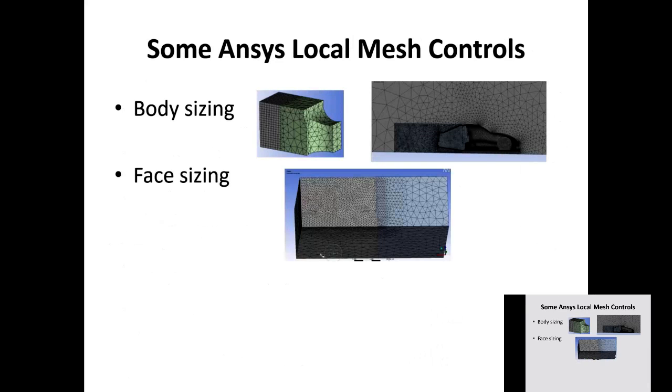Yeah. So there are some local mesh controls. What is meshing now? Here, in this area you have a nice cube, basically rectangular. So you can have rectangular cells here, but here you can't have a good rectangular cell. Therefore, you want to use tets as grid cells.